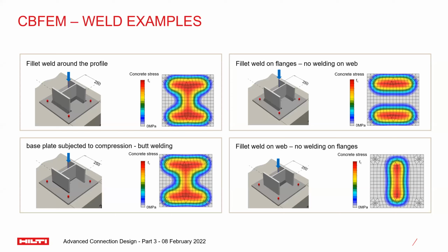All right, so here are some examples of the welds. The user has the choice of placing the welds under any segment of the steel section, be it under the web or the two flanges, etc., or stiffener welds, or custom stiffeners, again, anywhere you want. In case fillet welds are not sufficient in strength, an option of full penetration welds, or in other words butt welds, is also available in the software.